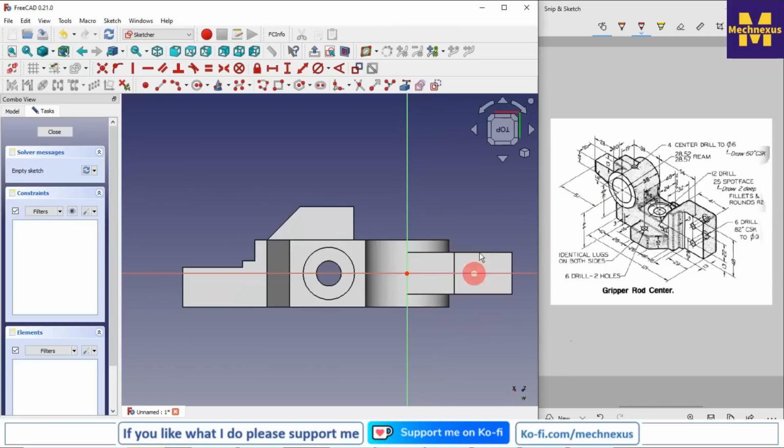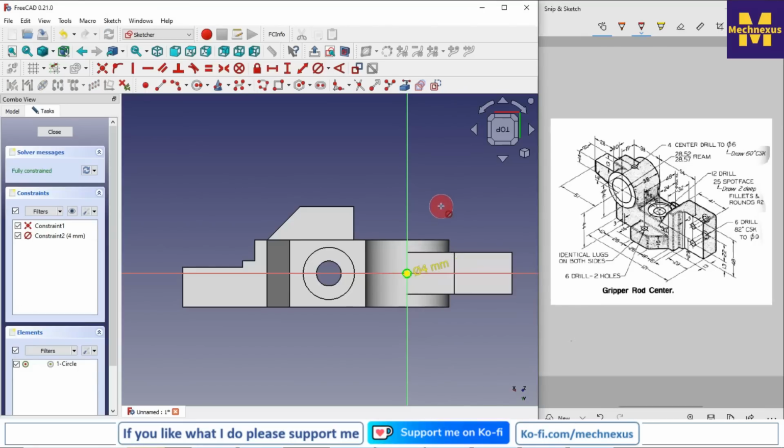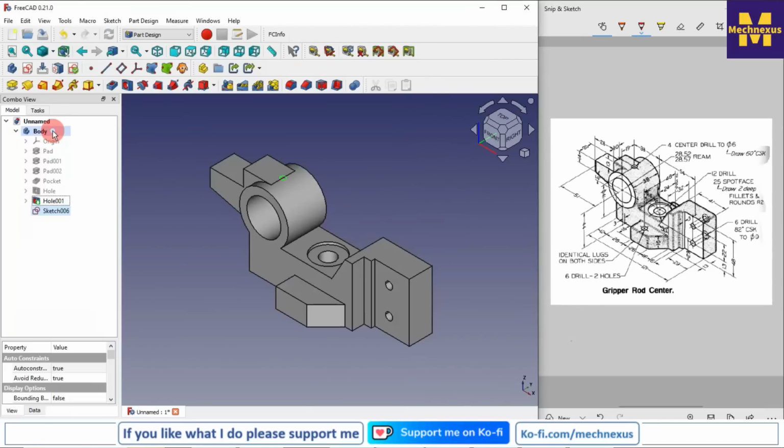So we will simply select a circle and create a circle, and we will give the dimension. So this is the 4 mm drill to dia 6 at 60 degree. So we will select the diameter and give it a 4 mm, and we will close it.